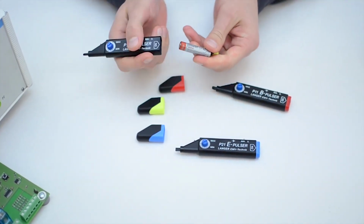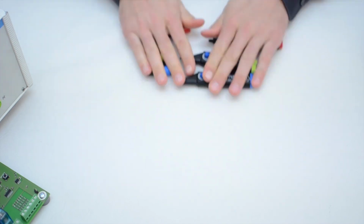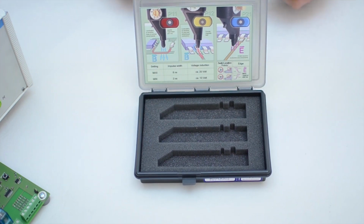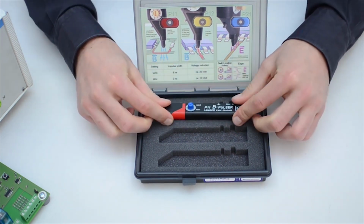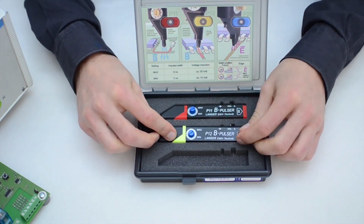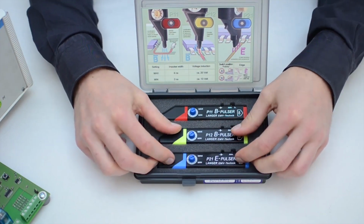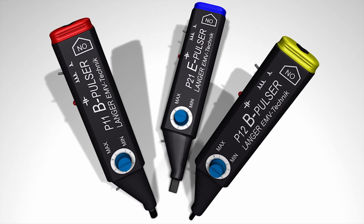We have compiled the 3 most important mini-burst generators for electric and magnetic disturbance fields in the practical P1 set. This includes the P11 for a focused magnetic field, the P12 for a vortex magnetic field, and the P21 for an electric disturbance field. Unlike conventional generators, these mini-burst generators enable you to pinpoint any weak spots in your electronics.